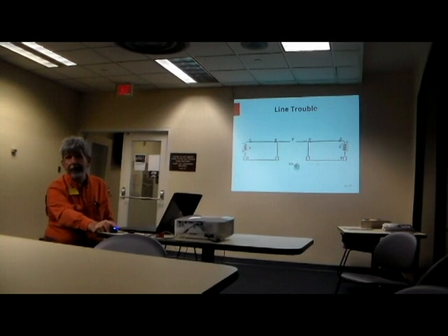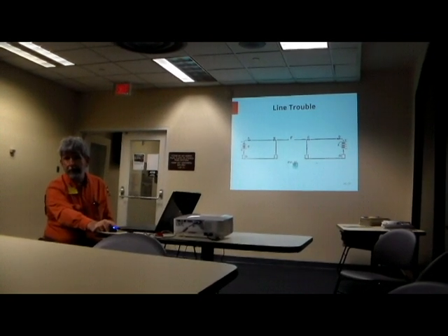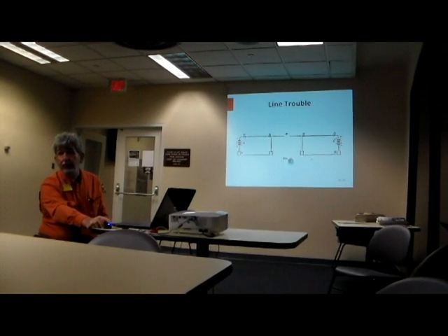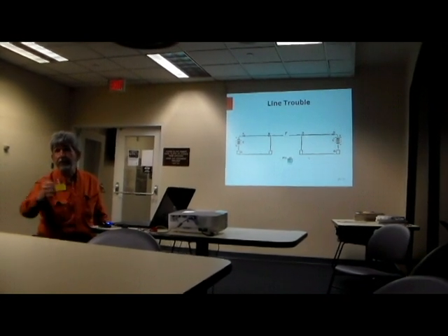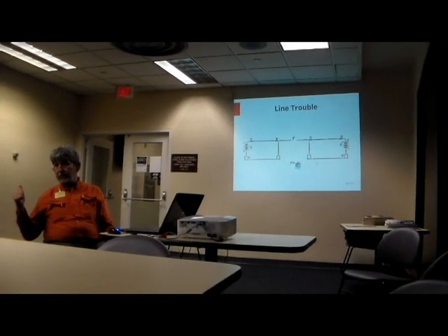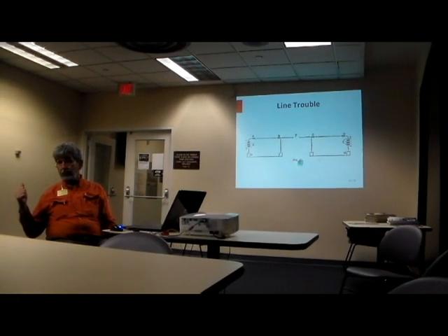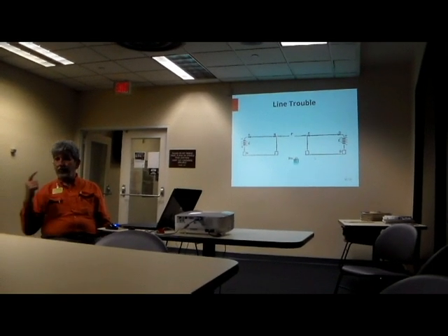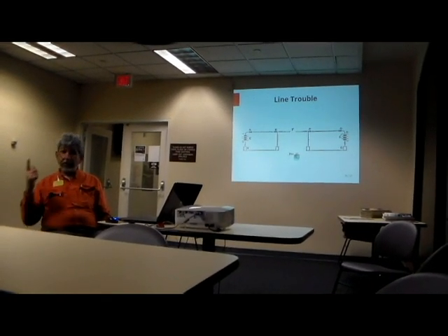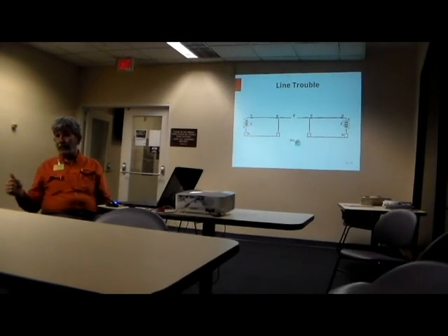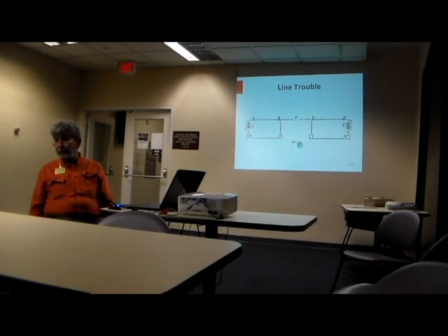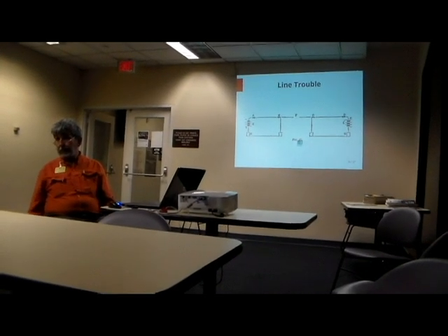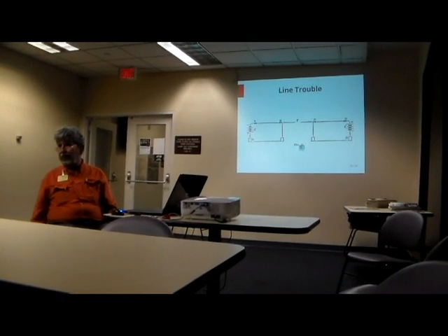Each station on either side of the break could strap the broken side of the line out of the circuit and strap ground into the circuit and be able to speak to at least one terminus the same way they always did, by ground return. And by the fact that the terminus stations could hear from this station and this station, they could tell the wire boss where to send the repair crew. And by other paths through other towns, they could get messages to the repair crews.